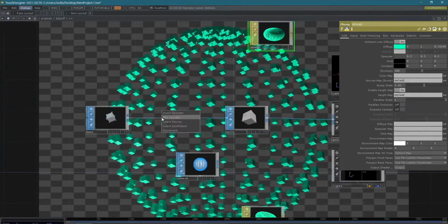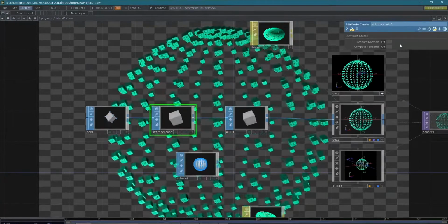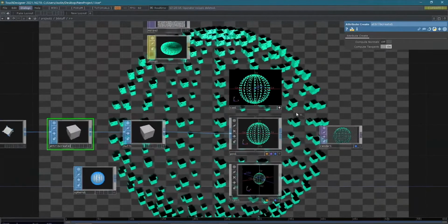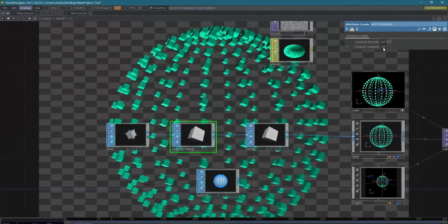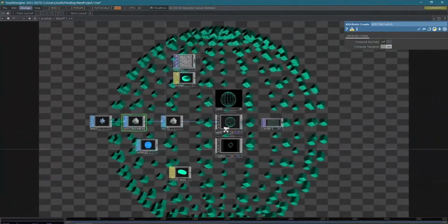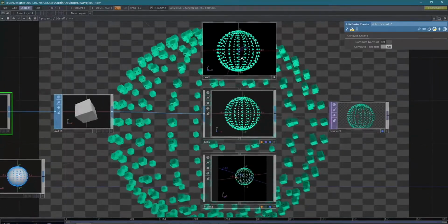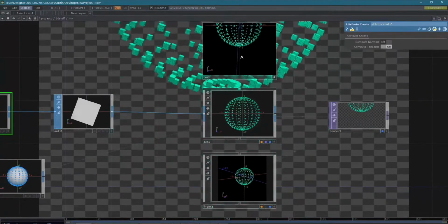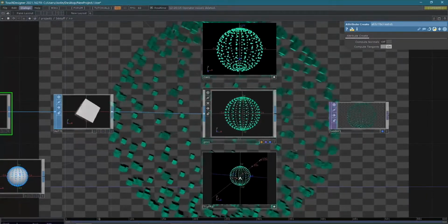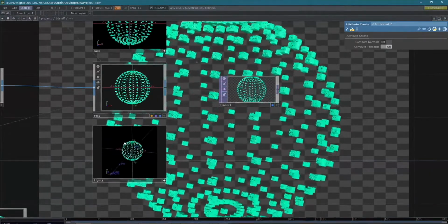So before the null here, I'm just going to move our box out, right-click, insert, and just attribute create. Hit that, and then you get 2 options for that, compute normals and compute tangents. So if I compute tangents, that error message goes away, and you'll see also now it knows how to compute those shadows a lot better. So things are feeling a little more realistic. If I move my camera a little bit, move the light. Cool, so now we've got some fun, drastic lighting things happening and movement.